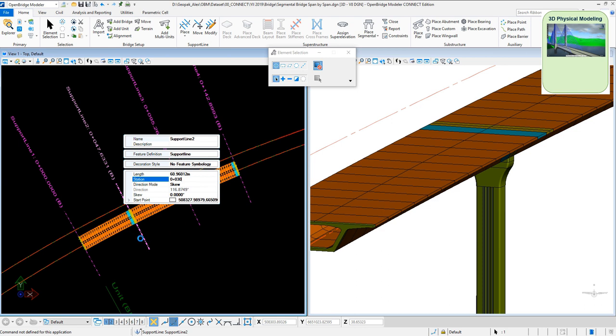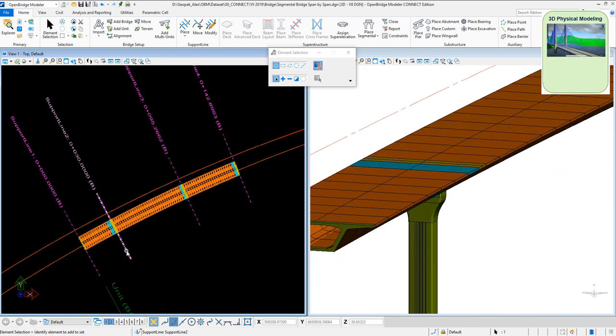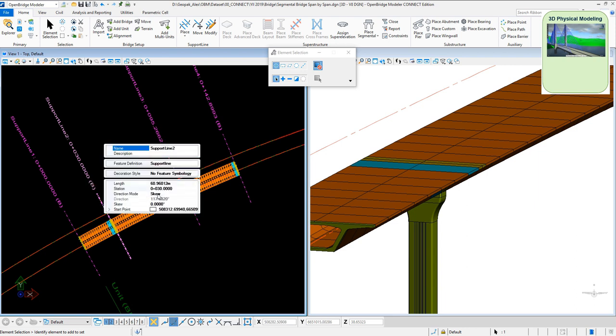without doing any scripts or visual programming. This is an application designed for bridges, so it understands the elements that belong to the bridge. It understands that the beams go below the deck, that below the beams should go the supports, but between the supports and the beam there should be the bearing supports, for example. So all those options are available to the user for starting to create the bridge.